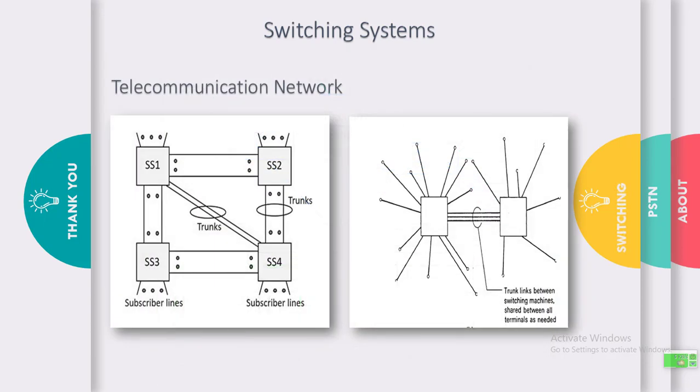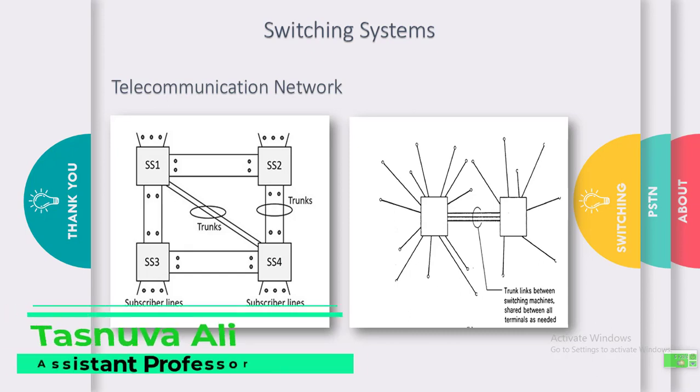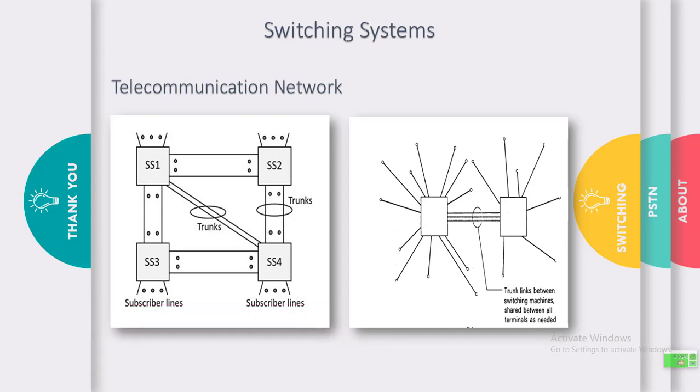Now you need to understand an important term, trunk. The trunk is the connectivity between any two switching systems or exchanges. For a trunk, you should remember it has more bandwidth compared to the subscriber bandwidth, that is the bandwidth from the telephone set to the local exchange.